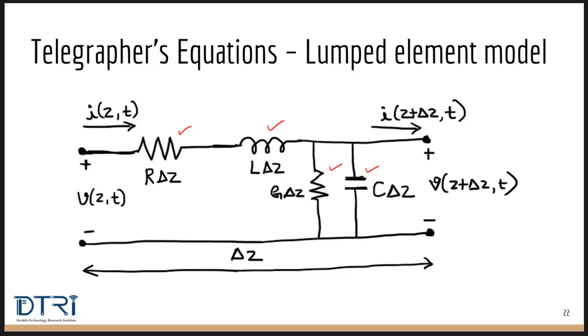So at microwave frequencies the wire looks as shown in this image, while at DC or low frequency it has only a resistance. You may have a question why I have shown two lines to represent a wire. This is one line, this is the other line, instead of a single line. That is because every transmission line has one wire for sending the signals and the other wire is considered as the return path, or also sometimes used as ground or the reference path. All measurements are with reference to the bottom line.